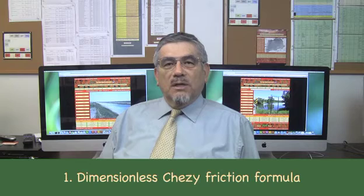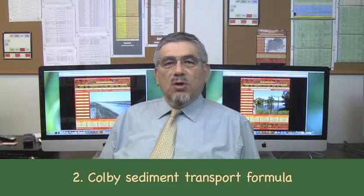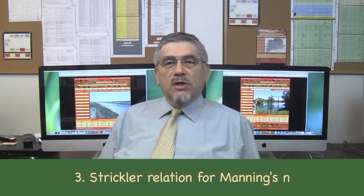The Lane relation can be expressed in dimensionless form by using suitable hydraulic and sediment transport relations. 1. The dimensionless Chezy friction formula. 2. The Colby sediment transport formula. And 3. The Strickler relation for Manning's n. The following derivations are strictly applicable to hydraulically wide channels. The dimensionless Chezy formula is